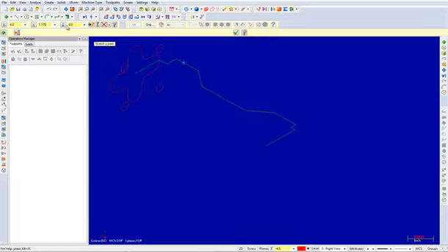Again, select the Fast Point command and input the coordinates as shown: -3.75, 0, -1.175. Press Enter. The point will appear as shown.